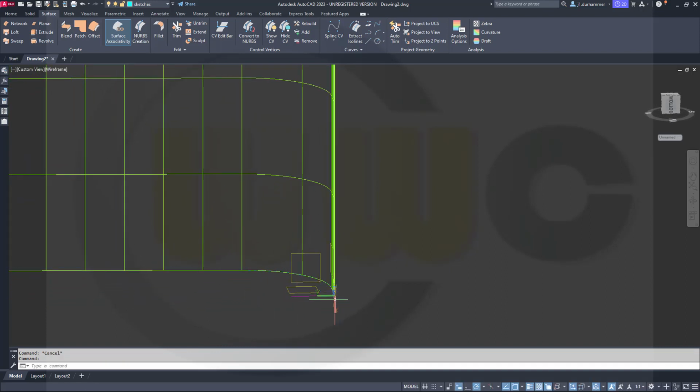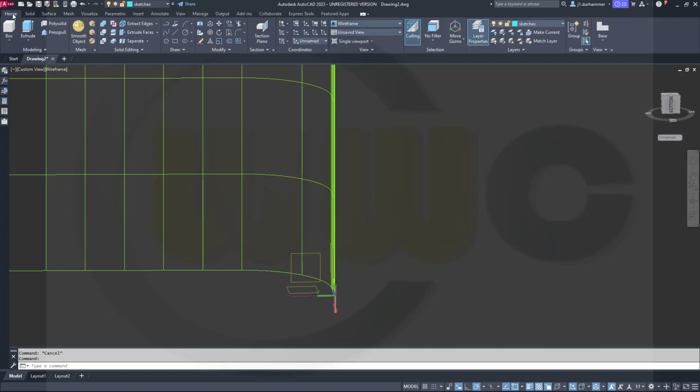So that's y direction, x direction. So go for an arc and choose one with an angle, start center angle. That's okay. Start point should be in this case at 0,0. The center point should be at 0,60, and the angle should be, let's go for this side with 60 degrees.